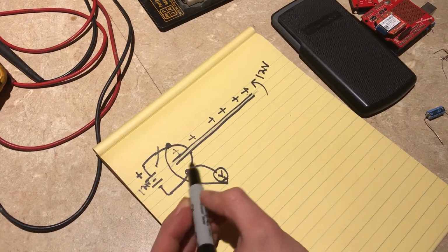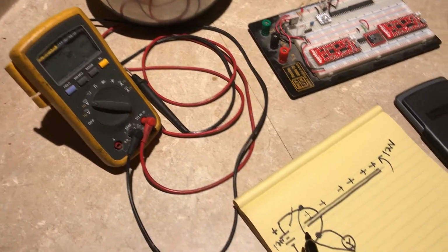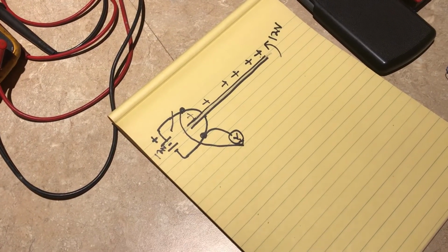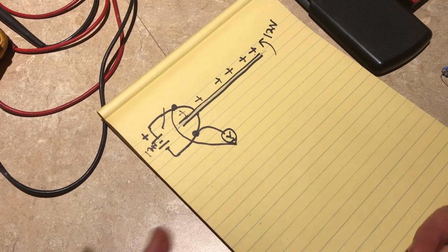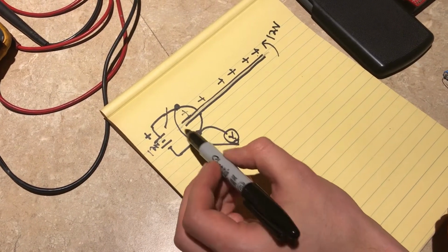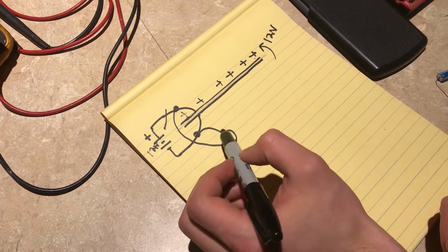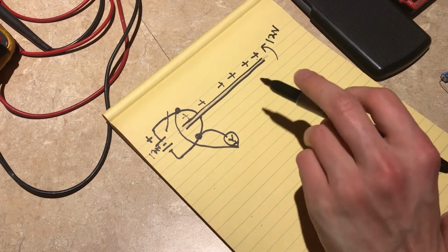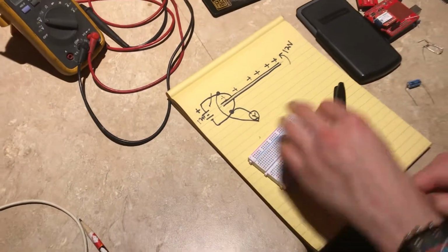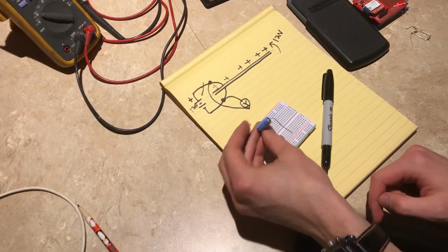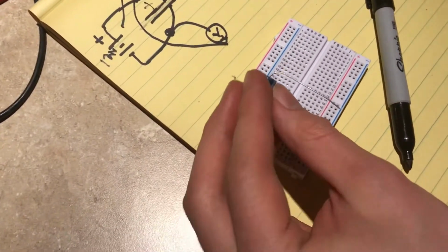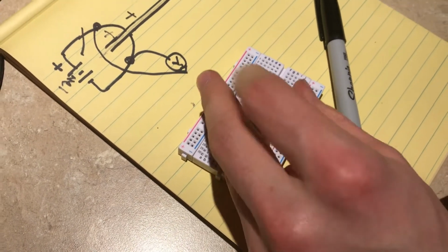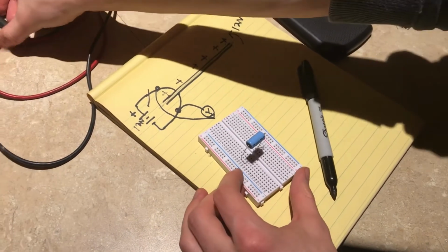That's my voltmeter. And you should read 12 volts. As you're reading 12 volts, you'll see it start to drop down because the voltmeter is going to dissipate some of that charge through its own measuring circuits, and we can actually see this. So this is my first demo I'm going to set up. This is an electrolytic capacitor rated for 47 microfarads. A farad, named after Faraday.